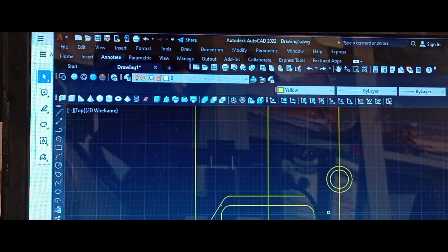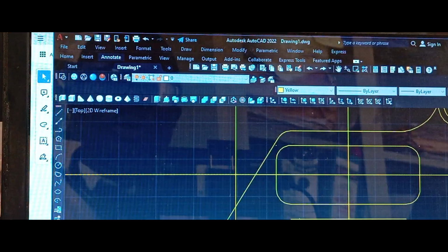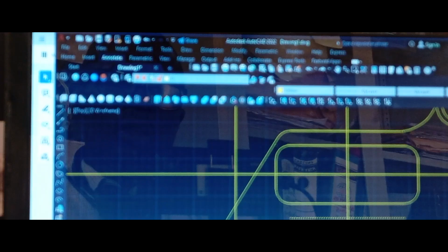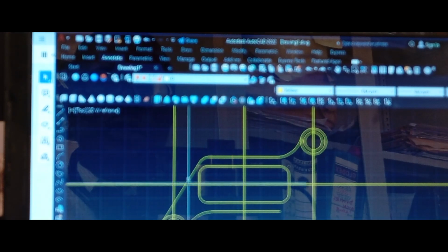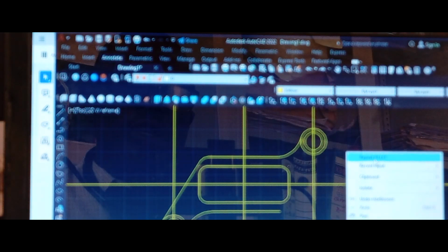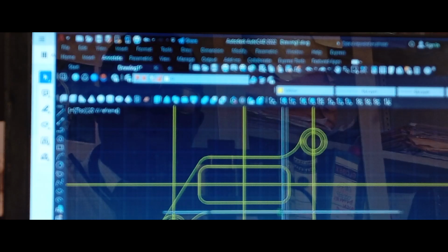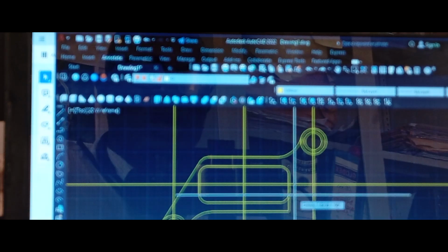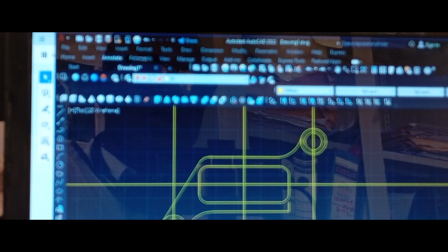Okay, radius 3. I'll just click here. Click here. I got it. So I say fillet with the same radius 3. I go here, I go here. I got that. See, I can decide to mirror this, but I'm not going to do that. I'm going to say, like I did here, 1. I'll fillet that 1, right?